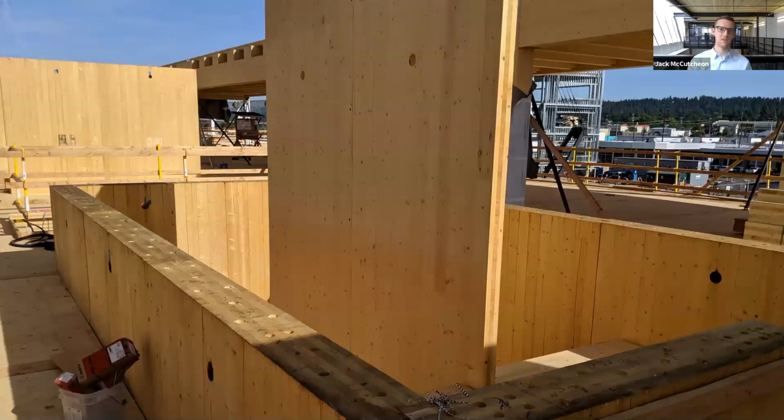Now, as I mentioned, since our building is 70 feet tall, obviously you can't get panels fabricated and shipped in that length. So we introduced a horizontal splice joint between panels about midway up the building. This photo shows the lower shear wall panels already installed. If you look closely, you can see some pre-drilled holes, and those are going to be ready to receive the threaded rods that get installed down to the lower panel and up into the panel above.